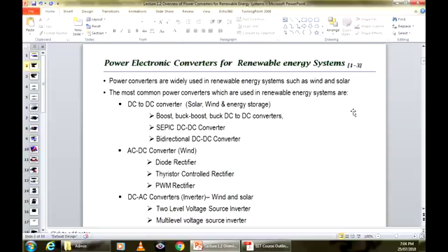That will be covered, I think, in week 7. And then there is the PWM rectifier, which is a diode rectifier in parallel with an inverter. Okay, we will show the structure later on, but we call it a pulse width modulated rectifier. Again, it is like a diode rectifier with power factor correction. However, if we have a PWM rectifier in a three-phase system or even in a single-phase system, we can control the power flow in a much more elegant and controllable way. All right, so that is the requirement for the PWM rectifier.